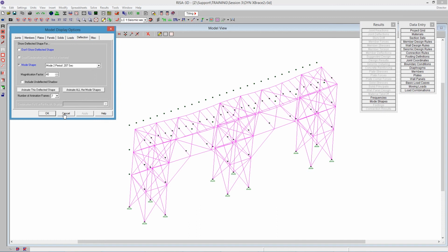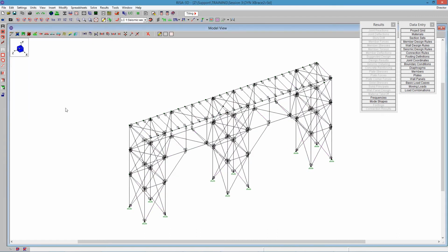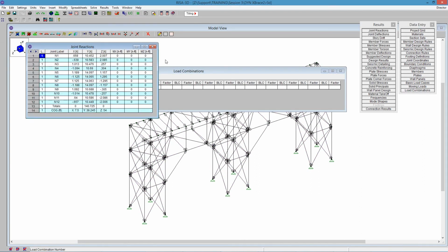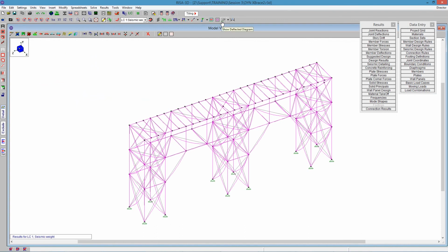If you're familiar with static design, where you see maybe just a portion of your model fly off, that usually tends to indicate that there's an error in your modeling. And that brings up a good point too, that you do need to make sure that your model runs as a static analysis. So it is always a good idea to start out with your load combination self-weight and take a quick look at your self-weight and see what's happening in the structure. If it's unstable, it won't run in dynamics as well. So you want to make sure that statically it's stable and then go to the self-weight, run that dynamic analysis. That's a common problem where the model's unstable before you even go to dynamic analysis. So let's go back here to the presentation.